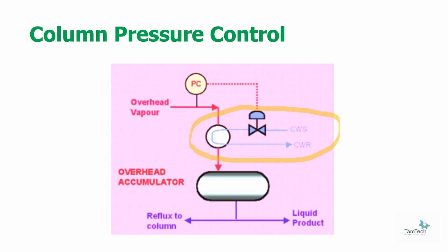Operation using cooling water can sometimes even cause fouling problems at low flow conditions for the heat exchanger, when cooling water velocity is low and also the outlet temperature is high. This is, as I mentioned, one of the most important and frequently used methods in the industry.